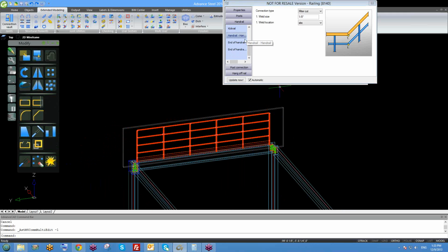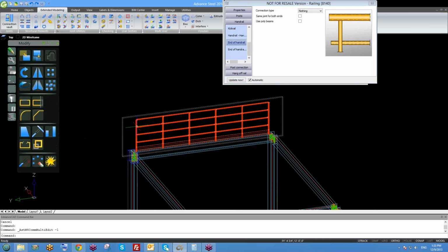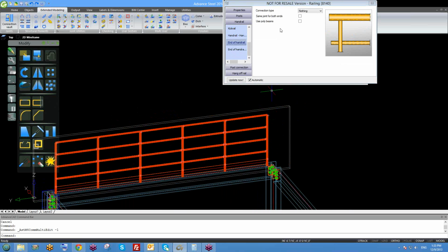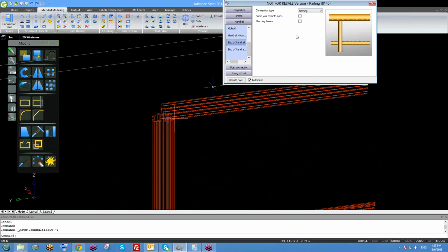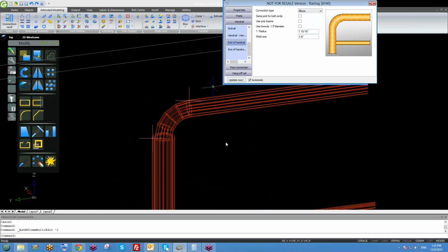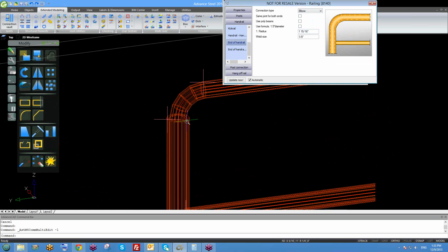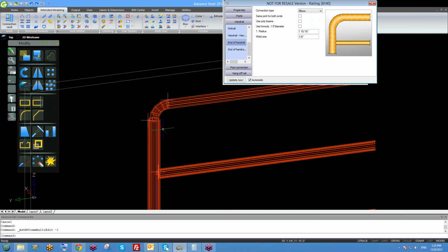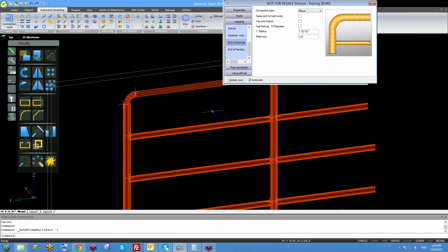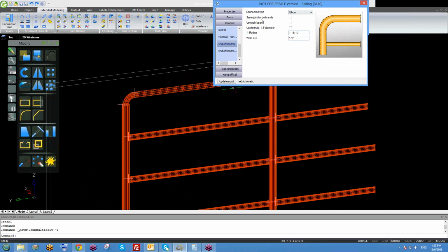And so we go to end of handrail right here. Start, beginning, starting, and right here end of handrail. Change this to elbow, this one here. If I change it to miter cut or change it to nothing, you can see how it changes. All right, middle elbow. So of course you need to have the same section, the same size to get this right, but at the moment it's just a training model. So same joint for both ends.